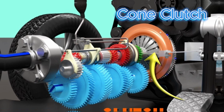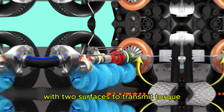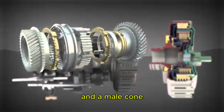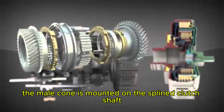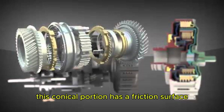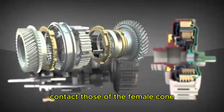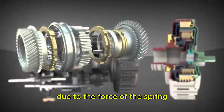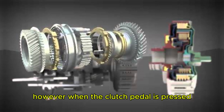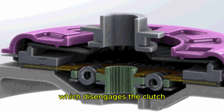Cone clutch. In a cone clutch, the friction surfaces are in conical shape with two surfaces to transmit torque. The engine shaft consists of a female cone and a male cone. The male cone is mounted on the splined clutch shaft, which slides on it. This conical portion has a friction surface. The friction surfaces of the male cone contact those of the female cone due to the force of the spring when the clutch is engaged. However, when the clutch pedal is pressed, the male cone slides against the spring force, which disengages the clutch.